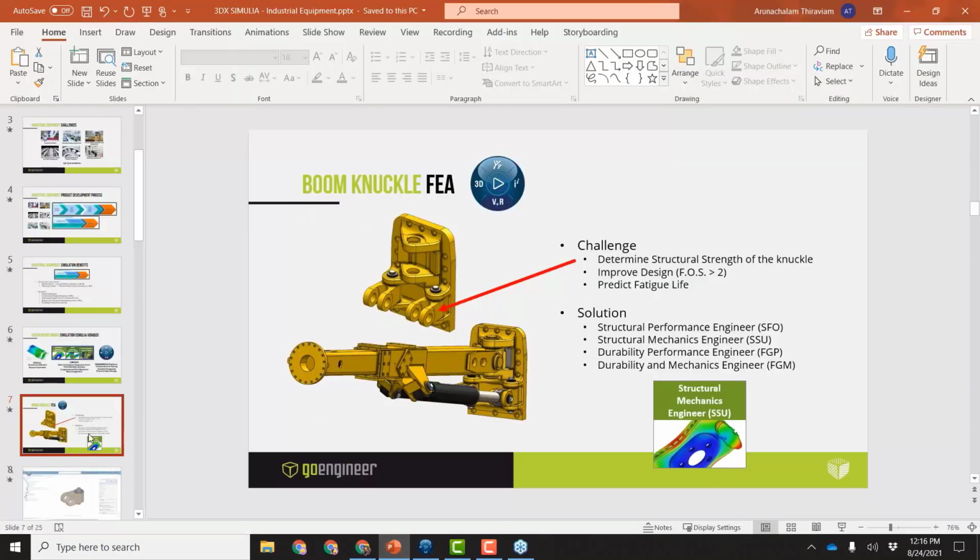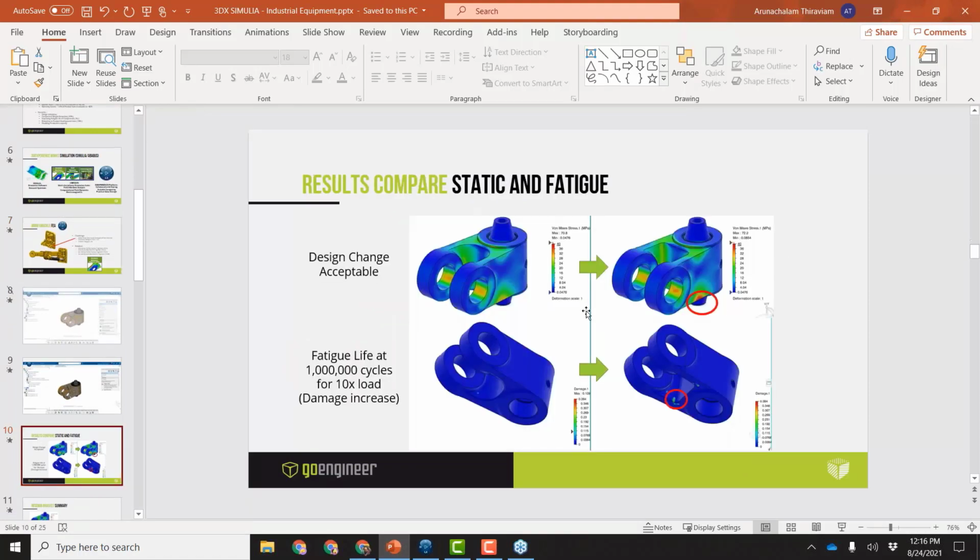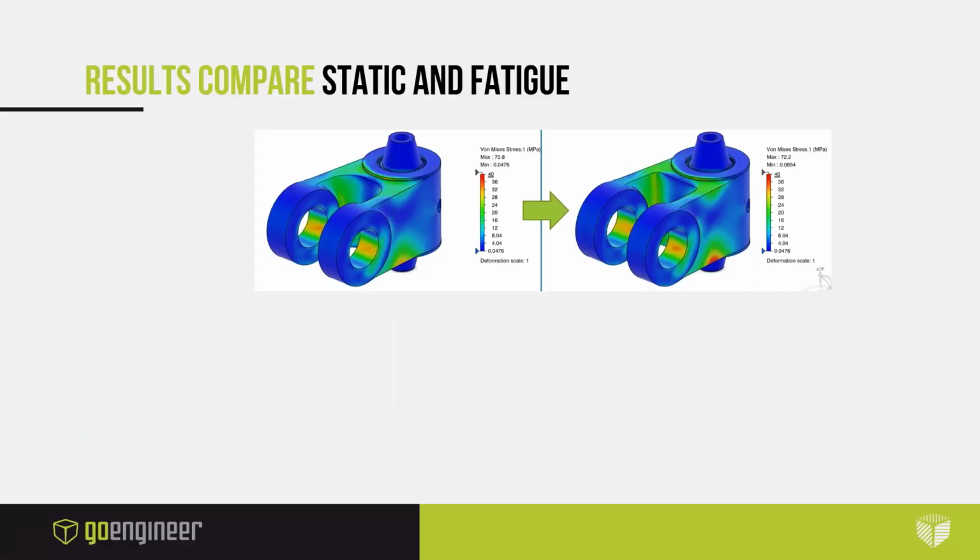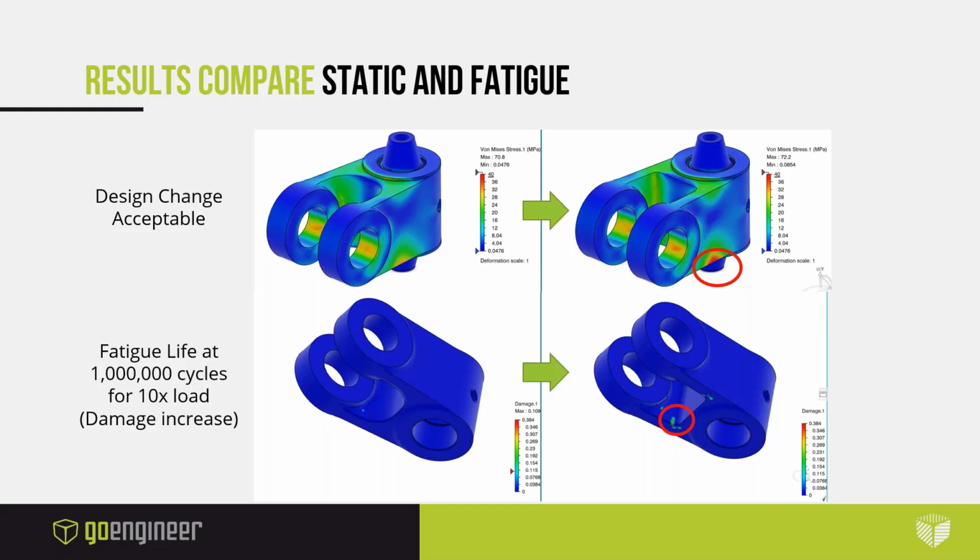Now, let me jump back into the presentation and quickly summarize this workflow. I was able to run the fatigue and static analysis with the interface, and make design changes just with the interface to compare the static results for both versions of the design. I did find that although the design is acceptable, there are certain areas that experience a lot more stress than intended.